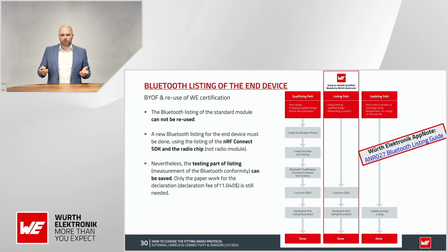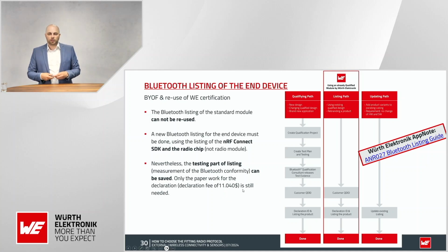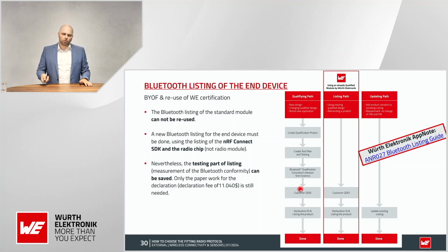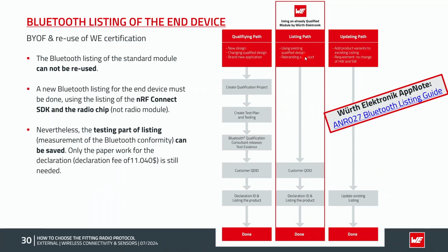And therefore, then you have to pay 11,040 euros here for your Bluetooth listing. And there are, for example, a few different possibilities. One possibility is you have to do the whole qualification process. That means that you have to test your device that it's really speaking Bluetooth. Or if you use a Bluetooth module, for example, from Würth Elektronik, there you can see that there is no qualification needed because the module already has it. And then you only have to do a declaration and only have to pay the money.